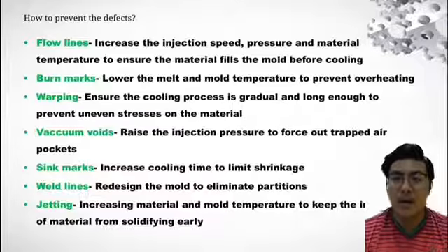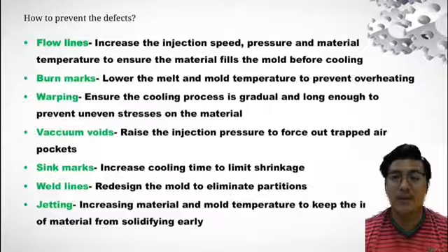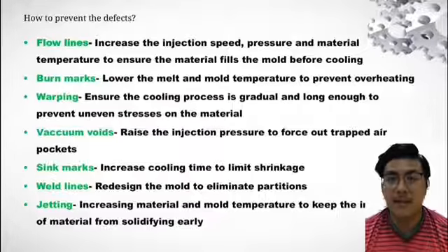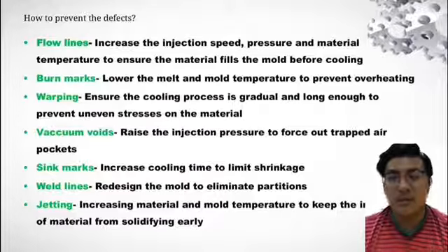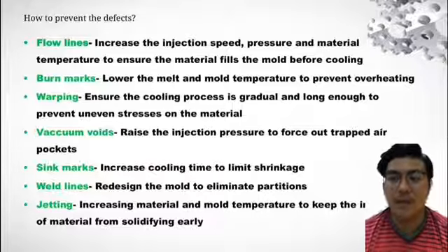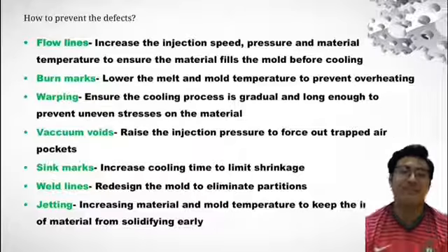Seam marks: increase cooling time to limit shrinkage. Weld lines: redesign the mold to eliminate partitions. And last is jetting: increase the material and mold temperature to keep the initial jet of material from solidifying early.